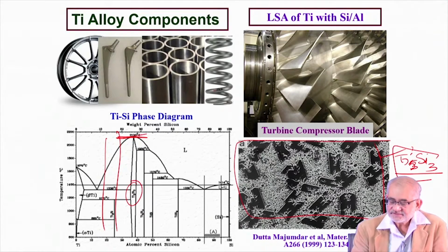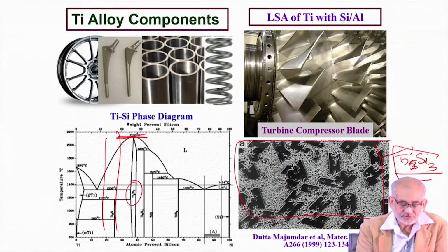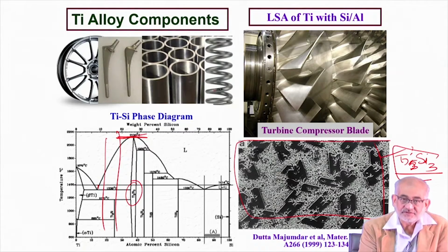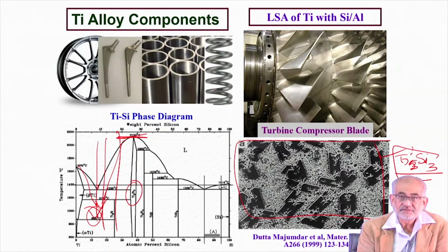So we create a surface which is about 30-40% covered with these faceted intermetallic phases, and another 60% or so also is coming because of the eutectic here. But the advantage is that we are able to create this with just a few percent of silicon, because if you refer to the corresponding T0 concept, and if you quench very fast and can go below the T naught intersection point, then you can retain an extended solid solution. In this case, we didn't retain an extended solid solution, we allowed phase separation in the form of eutectic, but then this eutectic point actually got shifted because of fast cooling.